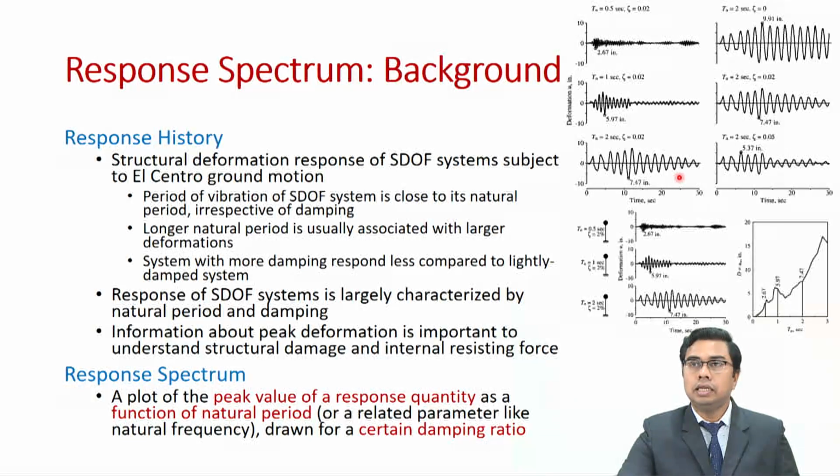The second thing evident from these plots is that longer natural periods are often associated with large deformations, which means that while the single degree of freedom system with a natural period of 0.5 seconds has a small peak in the structural deformation, the system with a natural period of 2 seconds has a larger peak.